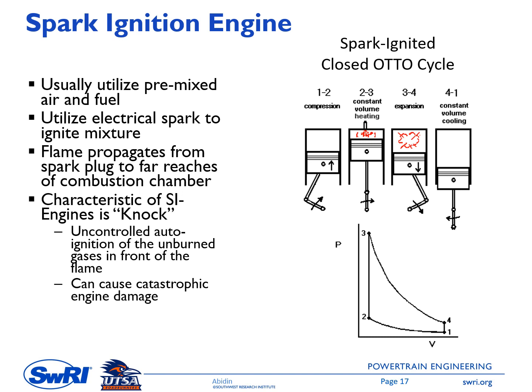Another characteristic of the spark ignition engine is that it utilizes an electrical spark to ignite the mixture. This figure shows a schematic: this one is the compression process, and at the end of the compression process the spark will ignite the mixture, and then there will be a combustion process here, and then this one will be a kind of blowdown process.